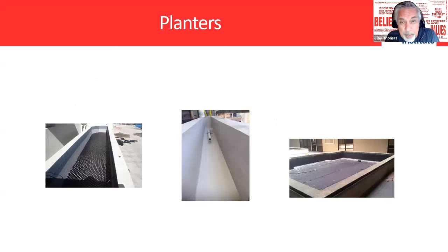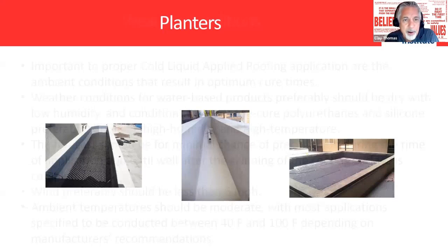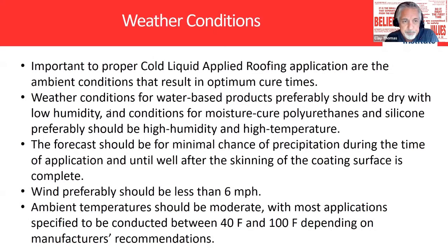You look at the one in the middle, you can barely stand in there, and you have to work in there, and you have to apply fabric in there. You have to detail that pipe where it comes up. You have root guards in there. You have drainage mats and protection layers. So being good at a planter is almost an art in itself.